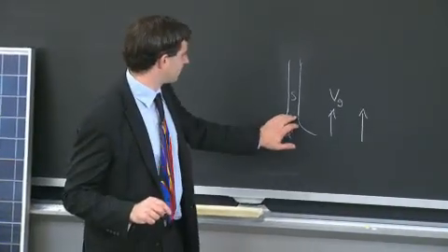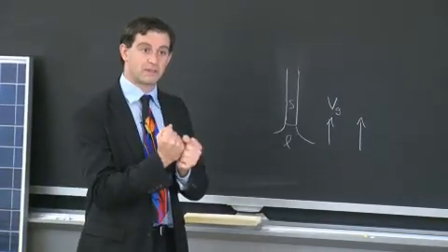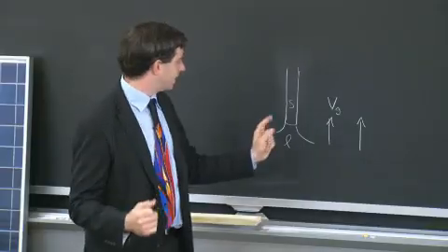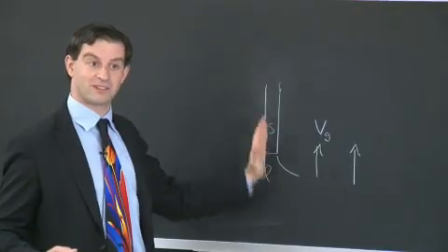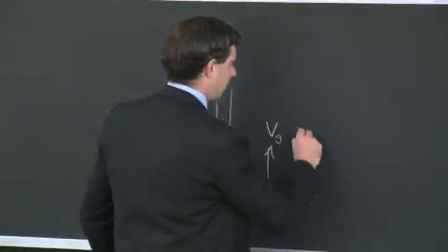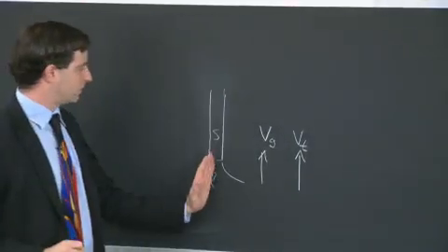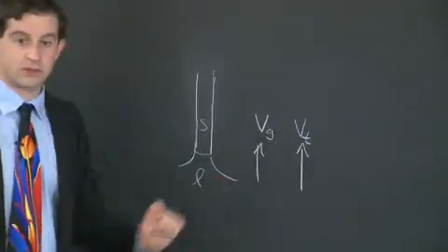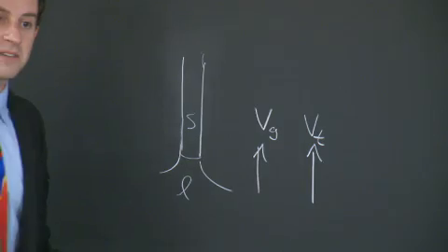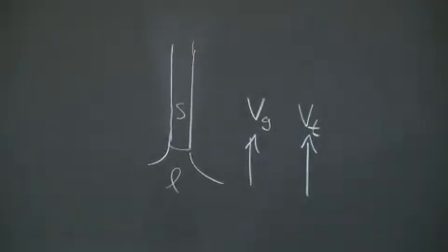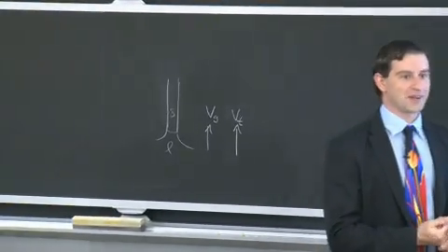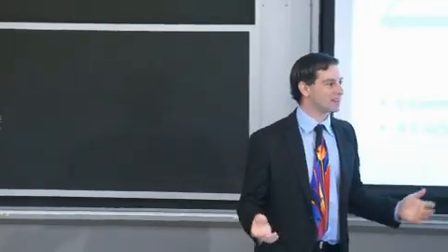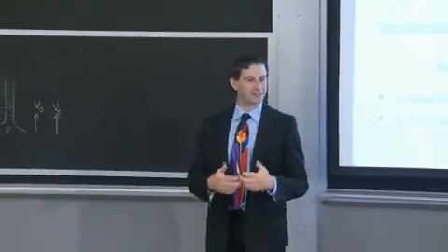So you have liquid silicon solidifying here. During the solidification process, there is heat released, and that heat has to be conducted up the solid and then radiated outward from the fin, from this thin ribbon. So the direction of heat extraction is also parallel to the direction of growth. What that means is the growth velocity will be limited by the speed at which you can extract heat up the ribbon and then radiate it outward. So there are many ideas tossed around about potentially growing in media that are able to extract heat faster than the radiative transport.